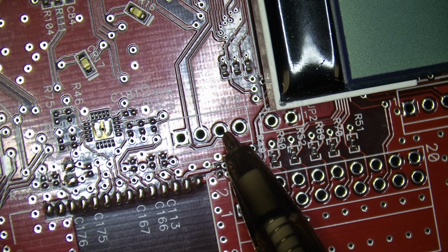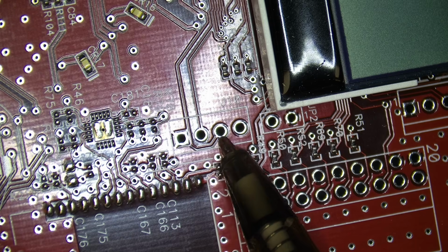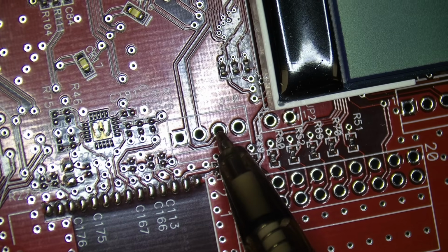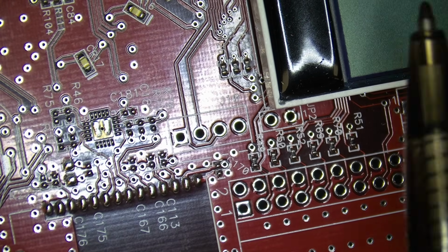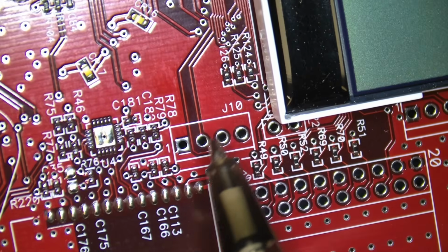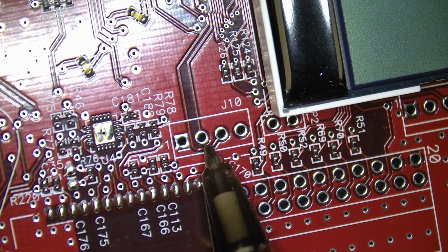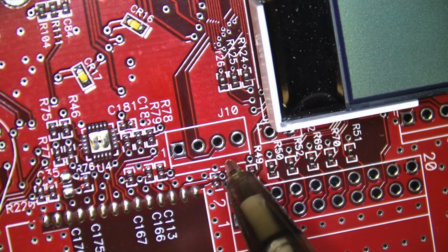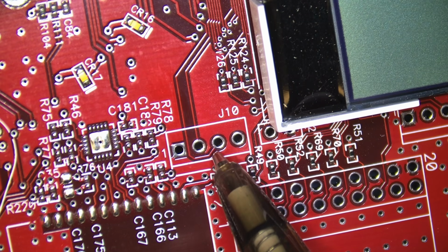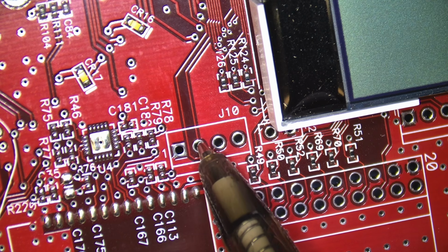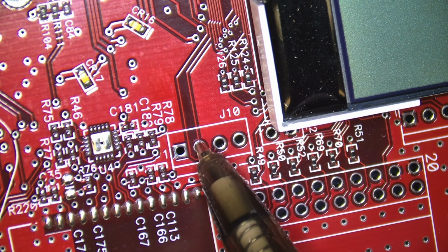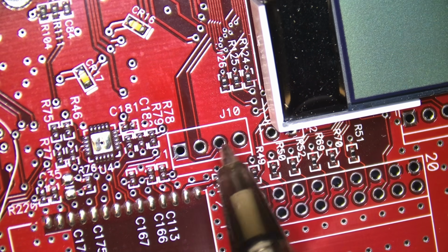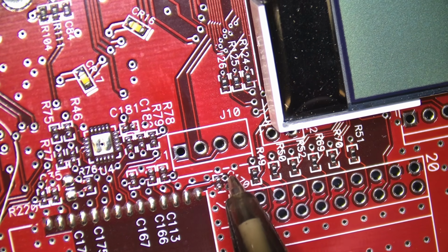So now you just got to figure out which one of these is the TX and RX and what the baud rate is, because UART is asynchronous. That means there is no clock signal. You just have the RX and TX, and you're relying on that baud rate to tell you what's going on. So notice how these two right here have a tiny, tiny little wire. See that little connection right there and that little connection that goes all the way up there? Those are almost definitely going to be RX and TX.